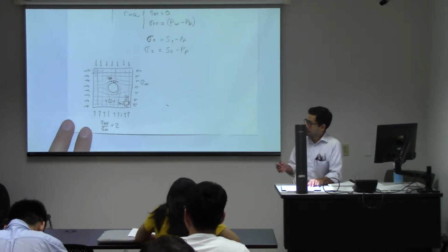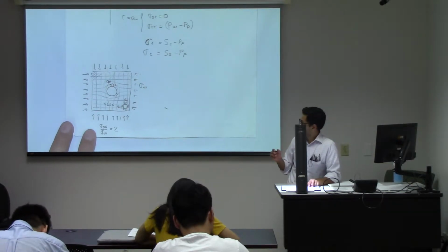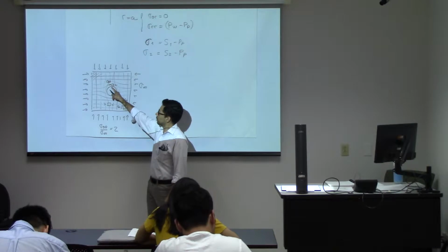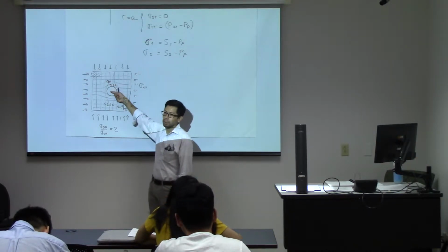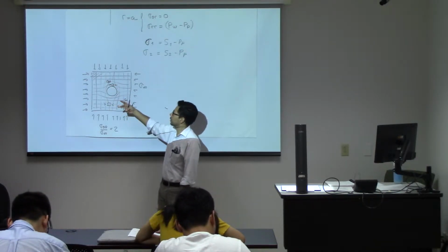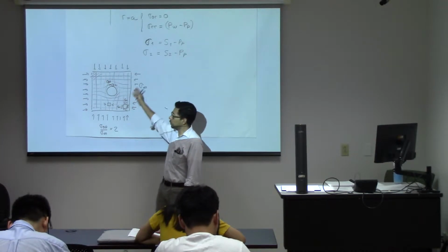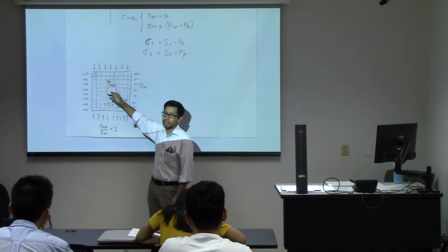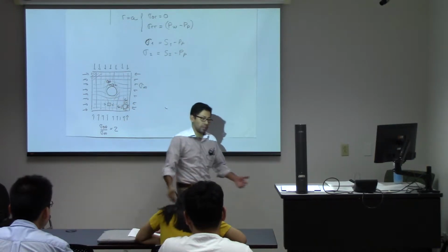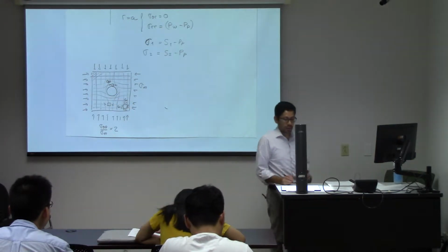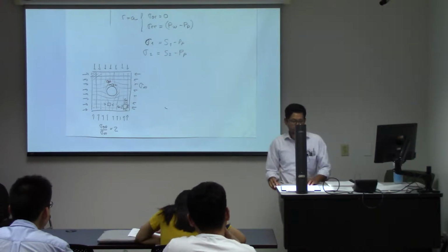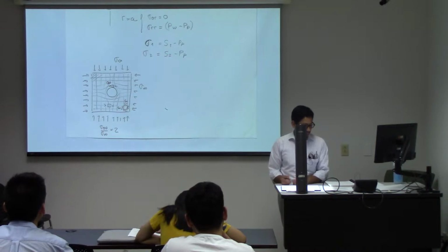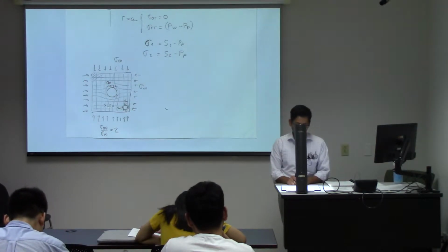And what that means is that just because of the presence of a cavity, around this cavity in this direction, we have a compression which is twice as much as the far field stress. So we didn't add stresses to the far field. We just added the cavity. And because of the presence of the cavity, now you have 2 times the stress that you would have in the far field, even if you have, remember this, an isotropic stress condition.